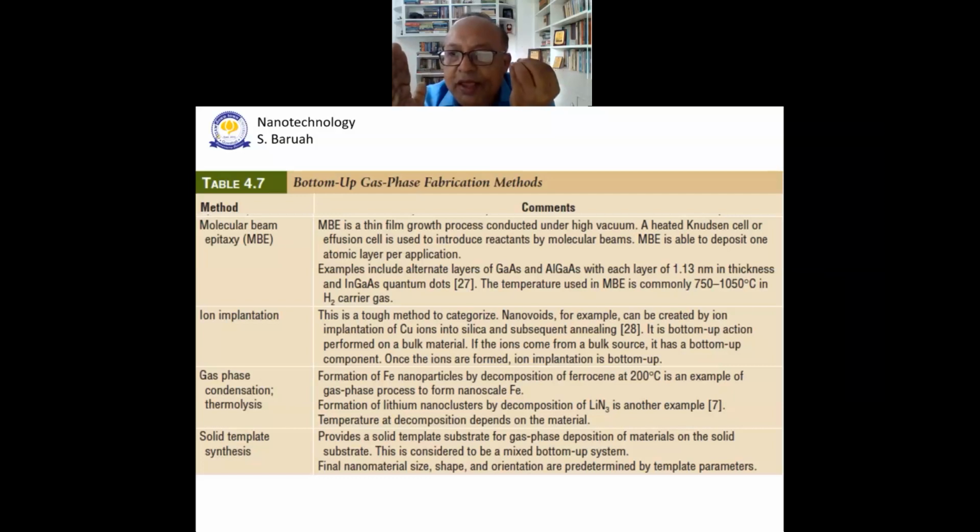And the same process, the strength of the electric field will decide what speed this will move. Higher the strength of the electric field, more will be the velocity of these particles moving down. All right, and that's precisely why we need to charge up an atom, why we need to convert an atom into an ion before we use it to strike a substrate.